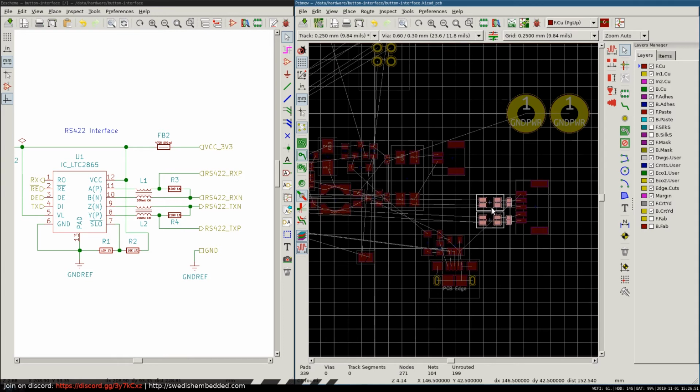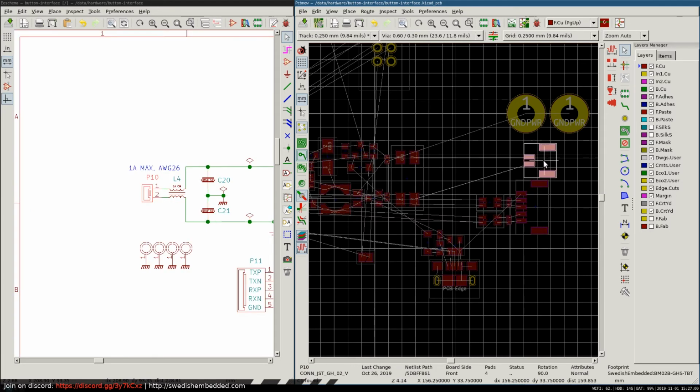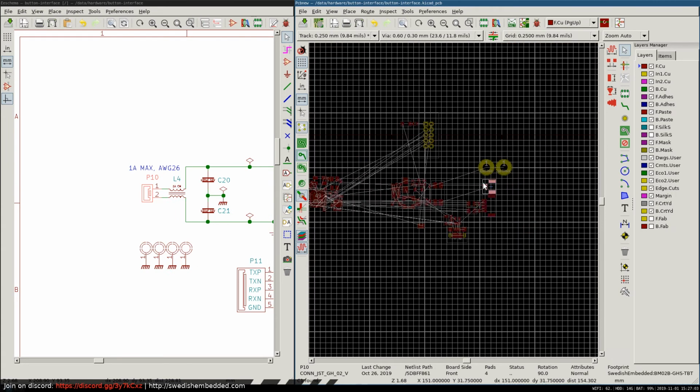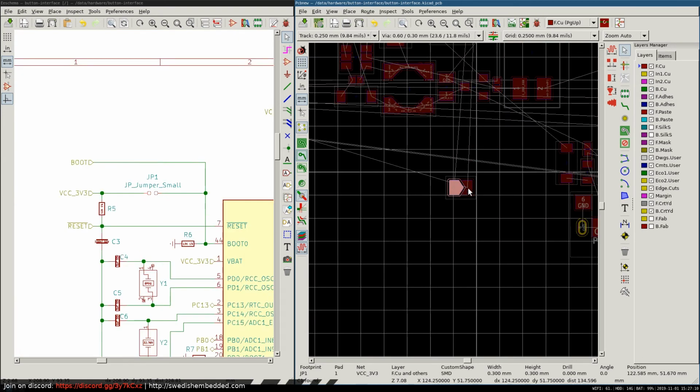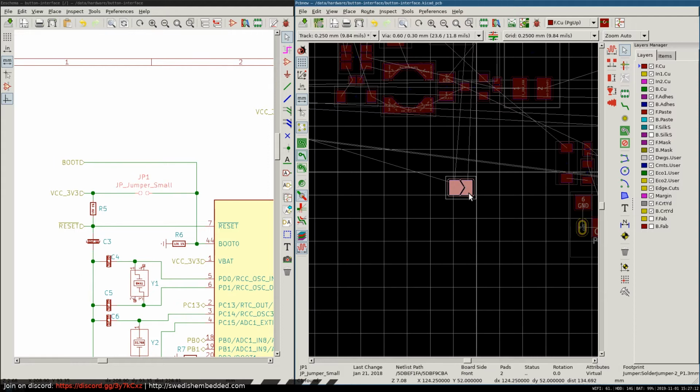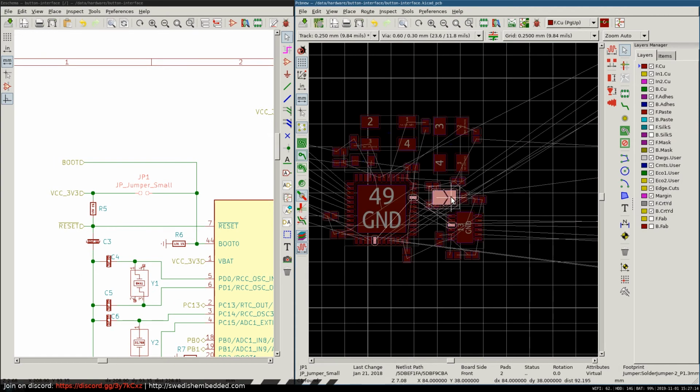So this can filter anything coming out from here, so nothing comes out from here to the transmission lines. And then I'll just combine these two into one. So it's just going to mean adding another pin to this connector, which is very good. Then we have this jumper. This jumper needs to go here.